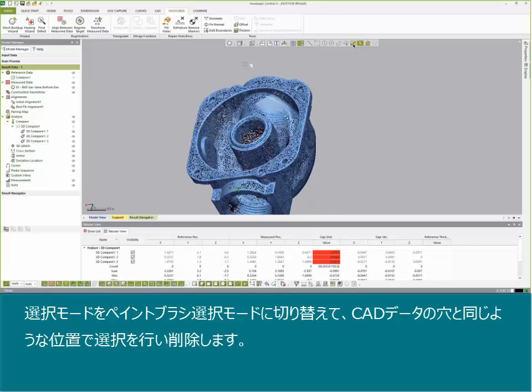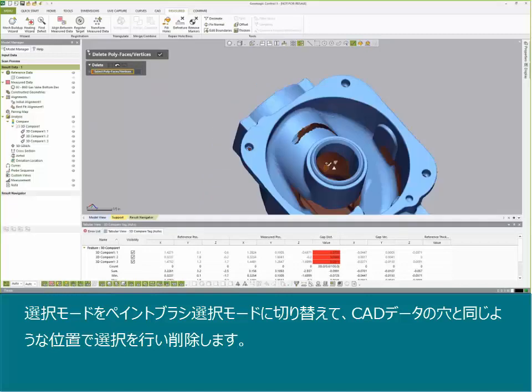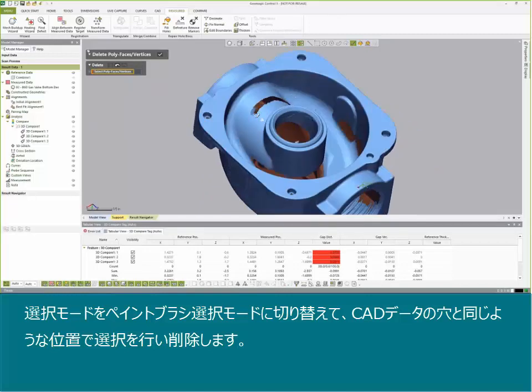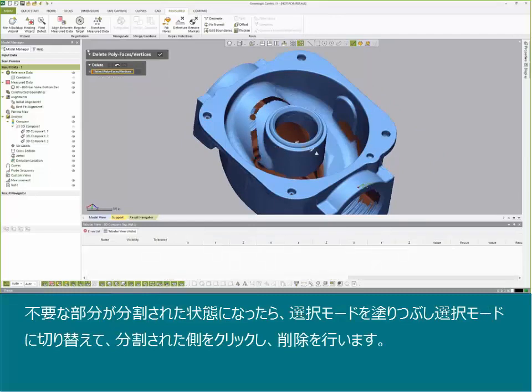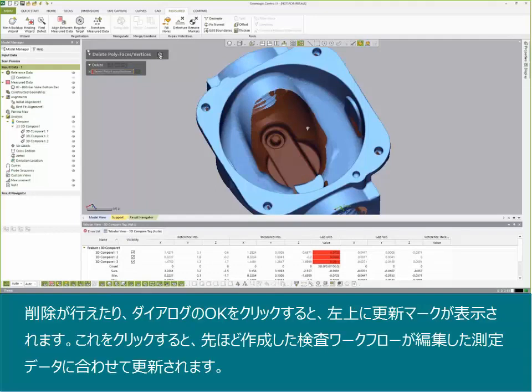Clean up our meshes, but what I'm actually going to do is come in and just highlight some of my data here of some things that I might want to get rid of. So for the sake of the demonstration, I'll pull out some of this data, and I'm just going to pull that entity out in the center because it's just not on our CAD. It's just a red blob on our color map if we don't exclude the data. Now when I hit OK, now that I removed that, you'll see this is where our nonlinear inspection really comes into play.